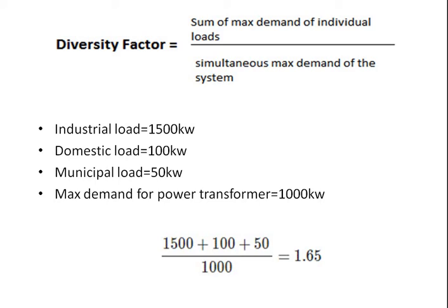Next is commercial load, consists of lighting of shops, electrical appliances. So the consumption of commercial load is during evening as well as in the daytime. Industrial load consists of heavy industrial machinery, so it varies during the different times of the day. And municipal load consists of street lighting system, water pumping system, etc. So the consumption of these loads is also not consistent throughout the 24 hours.